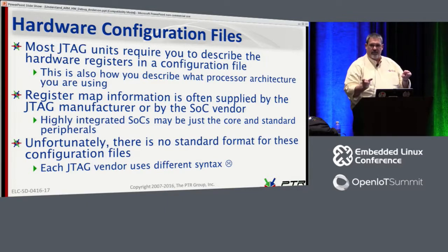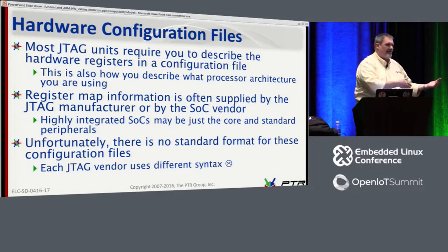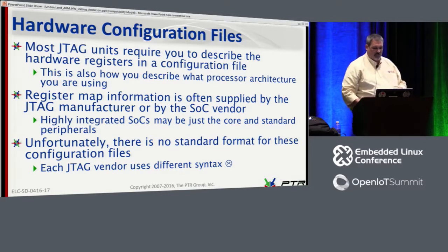So being able to use the JTAG in this very early boot cycle before Linux even begins to run gives us the ability to then take the actual register accesses we're doing and translate them into assembly language, because that's what we have to have ultimately to run in the early boot stage.